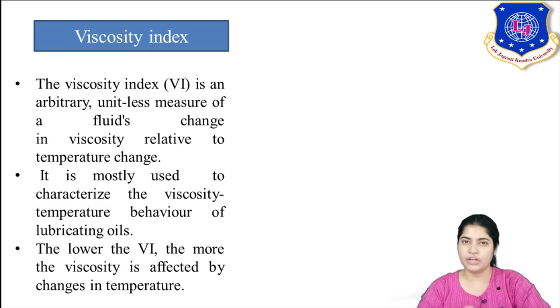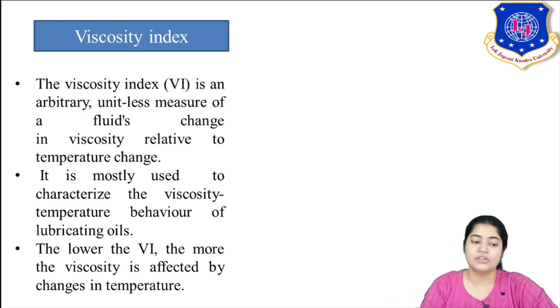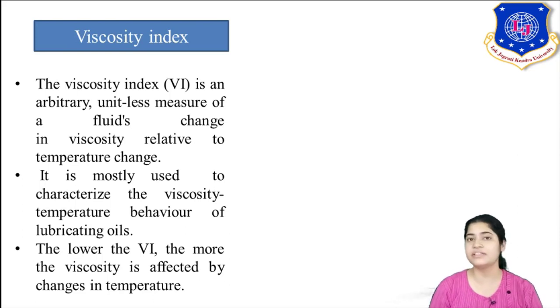Now, note down the important result here. The lower the viscosity index, the more the viscosity is affected by change in temperature. You have to remember this rule. A low viscosity index means your viscosity is highly affected by temperature change. It is very sensitive to temperature change. A little bit of temperature change can change your viscosity to a very high extent. That is the meaning of a lower viscosity index.